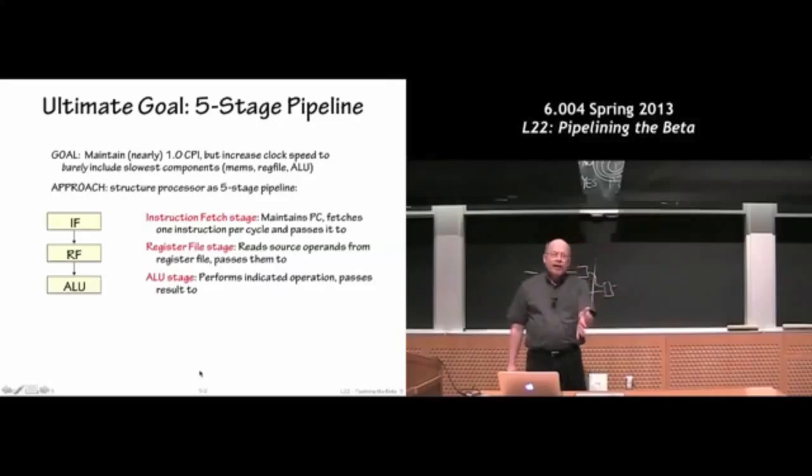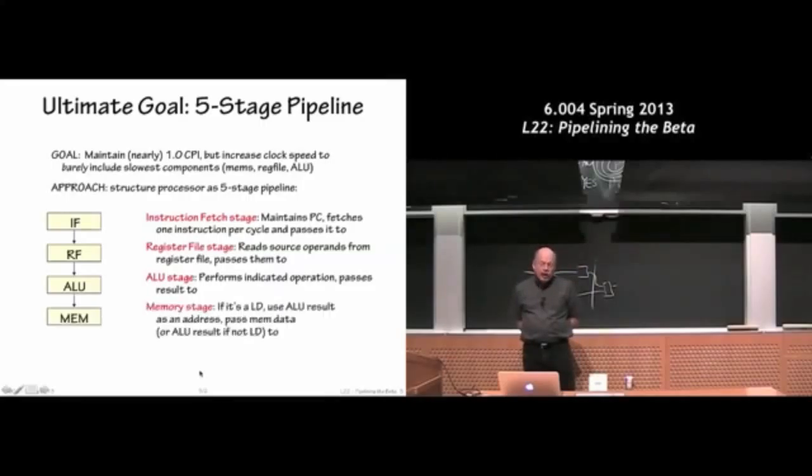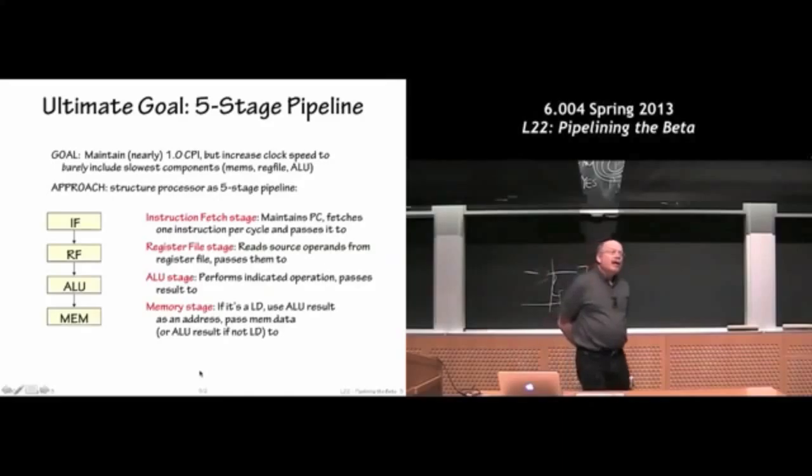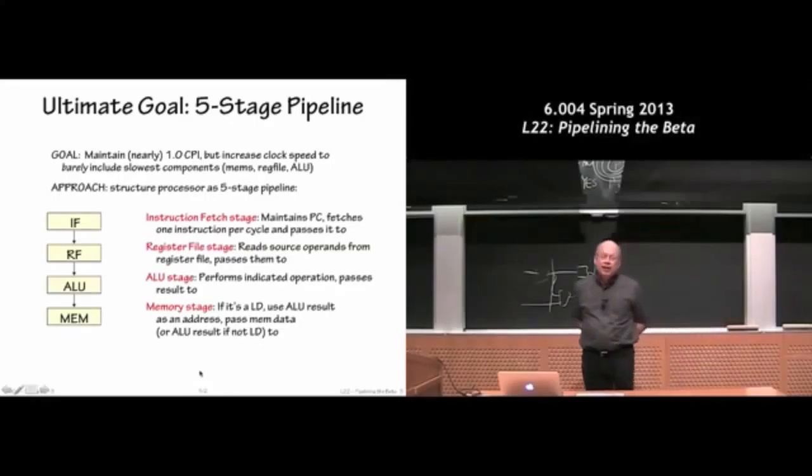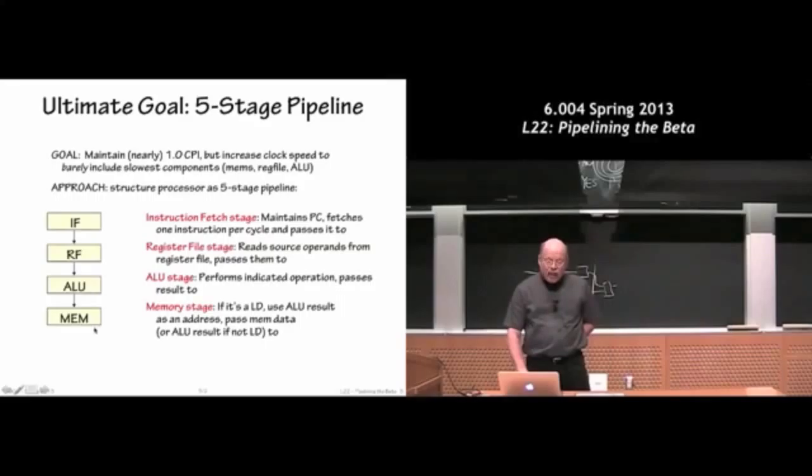Okay, so we're already on to step 3 here, and once we have the result from the ALU, for certainly the load and store instructions and the LDR instructions, we have to put in a step which is not needed by all instructions, but assuming that we use the same recipe to execute each instruction, we have to leave room in our recipe for loads and stores to go take the address computed by the ALU and to fetch the corresponding data, or to write new data into the location that was addressed by the result coming out of the ALU.